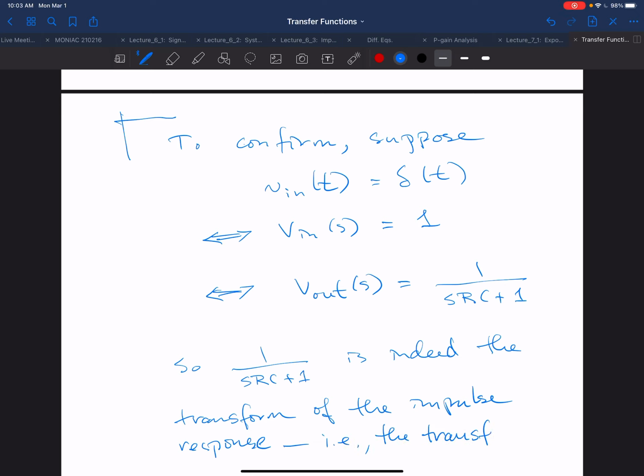So to find transfer functions, which again are going to be the main models that we use, we can simply take a differential equation that models our system, apply Laplace transforms to all the terms of the equation, and set the initial conditions to 0. In that way we can solve for the transfer function. So that's how we'll be getting transfer functions.